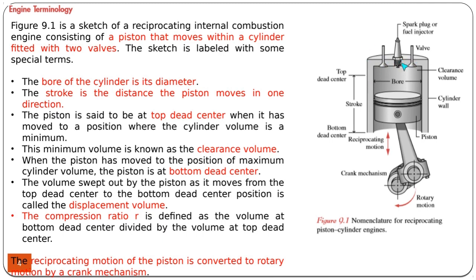And there are valves at the top of the cylinder. Some number of the valves are inlet valves, and some number of the valves are exhaust valves. There can be one inlet, one exhaust, or two inlet, two exhaust. It depends on the design of the engine. Differently, the gasoline engines have spark plug, which is not found in the diesel engines.